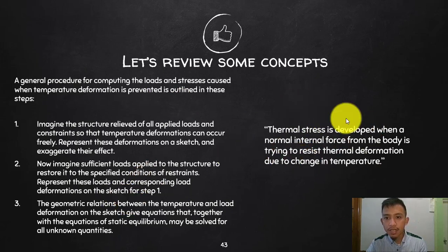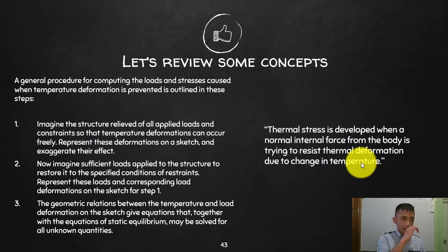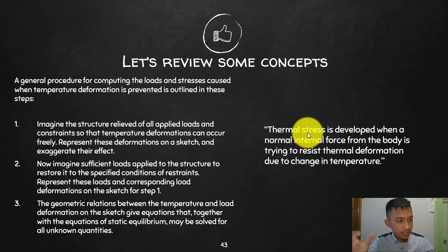And this is the additional note, wherein it says that thermal stress is developed when the normal internal force from the body is trying to resist thermal deformation due to change in temperature. Again, you will end up with an internal force because your member is being restricted, meaning it is connected to a certain fixed member. Okay, so that you will undergo a thermal stress. But if your member is free to expand or contract, then there will be no thermal stress.